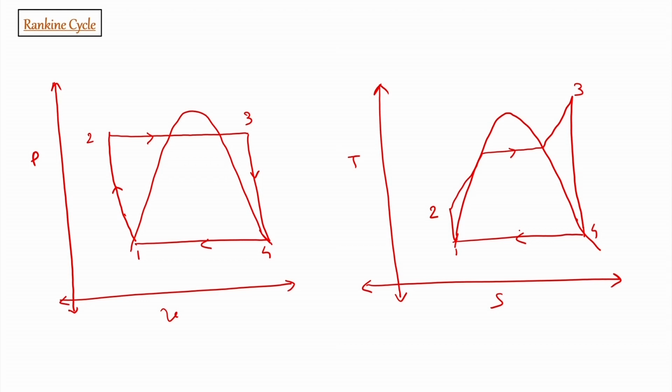So this cycle is giving us a thermal power plant, which is a steam power plant, and steam power plant has water as working medium, which is in liquid state in the 1 to 2 process, which will get converted into vapor state in the process 2 to 3. So 3 to 4 we will again have water in the vapor state, but 4 to 1 again there is a phase change. So this is a basic cycle which is again used for electricity generation, or in olden days it was used for locomotives, where one engine, which is steam engine, was based upon this cycle.